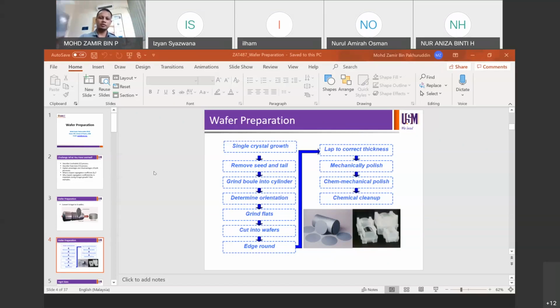Okay. So yeah, 25 pieces, 2 inch. So in this case, the wafers are all lapped to 275 micron plus minus 25 micron. Okay. So it's still lapping; we will see later what the lapping is like. So it's lapped to 275 micron plus minus, then they are categorized together for sale.